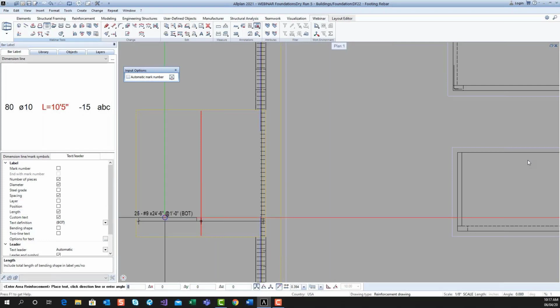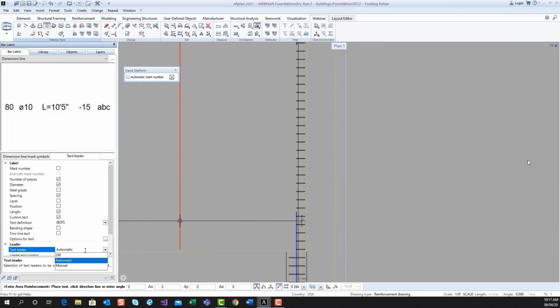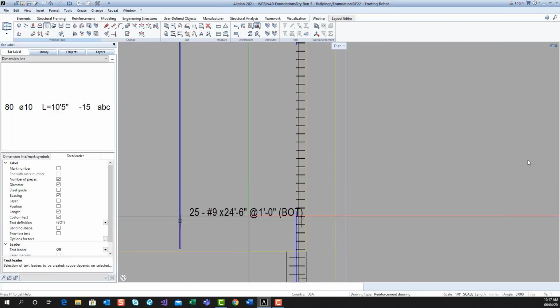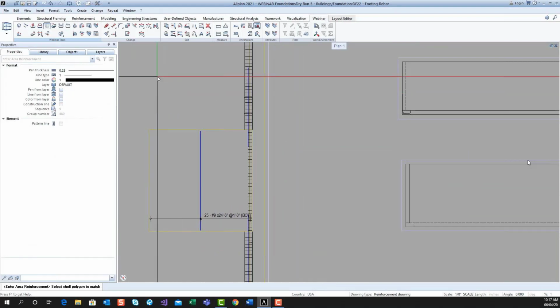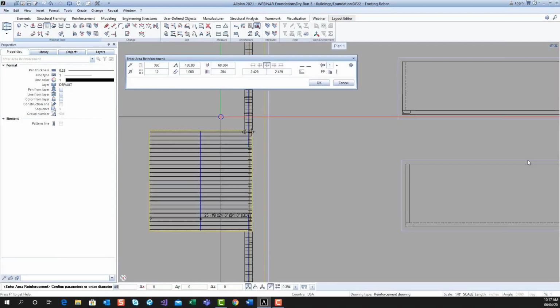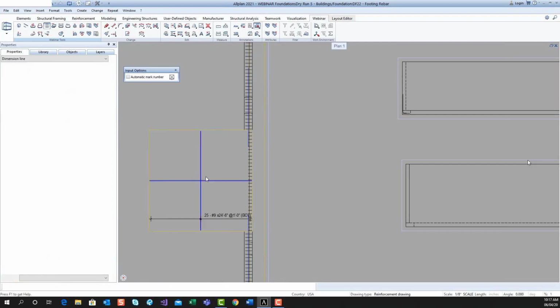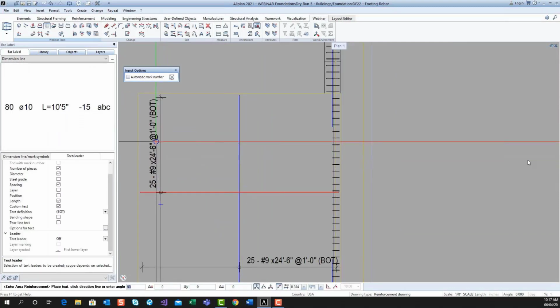The power of this particular tool you're going to see in the next spot is the ability to what we call match. When we do a match, it looks for an existing area reinforcement. When you pick on the bar, notice that the cover is automatically adjusted to the bar size, so it's bumped up into that. Automatically turns it 90 degrees. I go ahead and place my dimension. I place my bar and so on.